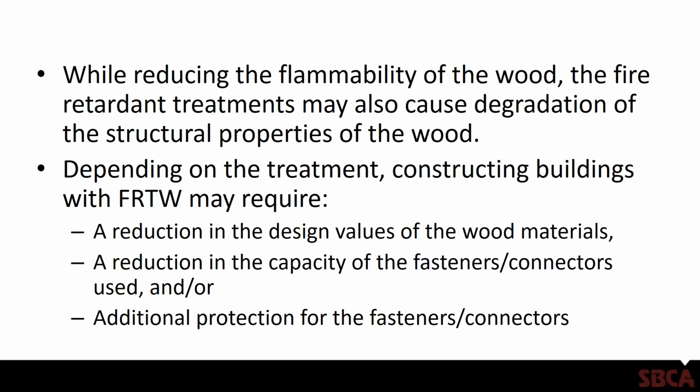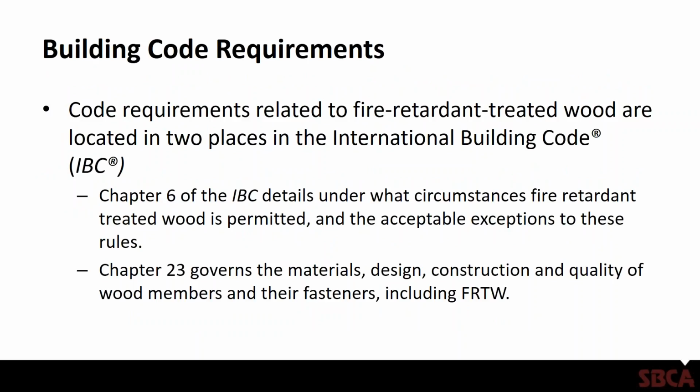For trusses, that would be the connector plates, and in some instances or applications it may also require additional protection for the fasteners and the connectors. So that's why it's fairly important to know what type of fire retardant treatment is being specified, and how to use that in the design of whether it's trusses, I-joists, whatever.